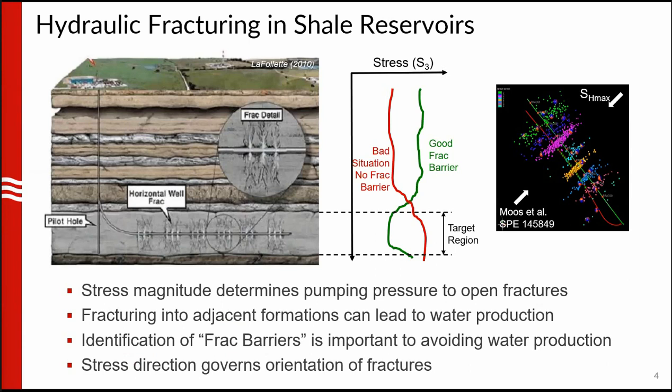Here's an engineering example, in a shale gas hydraulic fracturing setting, of why we care about stress. In a shale gas production setting, we have a certain target reservoir region where we want to extract gas from. And as I think most of you know, we access the gas through hydraulic fracturing because the formation is very impermeable. And in order to open up these fractures, you have to pump fluid in. The stress magnitude at that formation is what governs the pressure that's required to open the fracture.